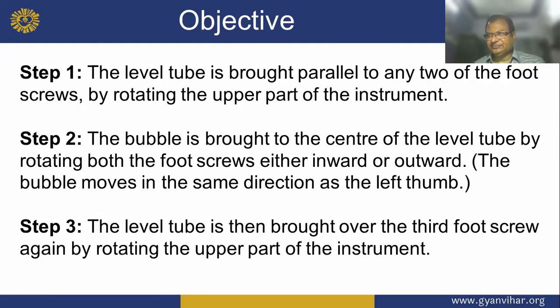And second, the bubble is brought to the center of the level tube by rotating both the foot screws, either inward or outward. The bubble moves in the same direction as the left thumb.